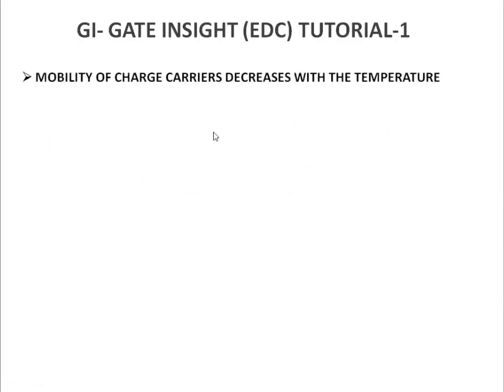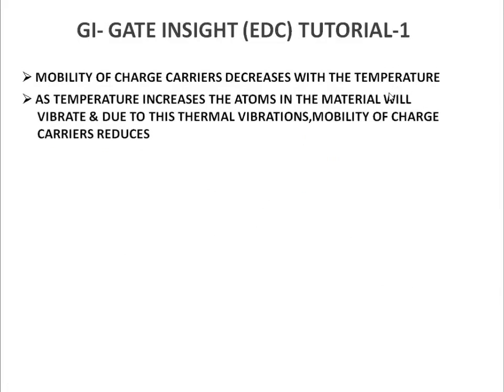The mobility of charge carriers decreases with temperature. As the temperature increases, the mobility of charge carriers decreases. What is the reason behind that? We will see. As temperature increases, the atoms in the material vibrate, and due to these thermal vibrations, the mobility of charge carriers will reduce.